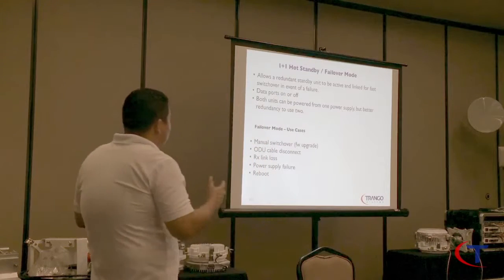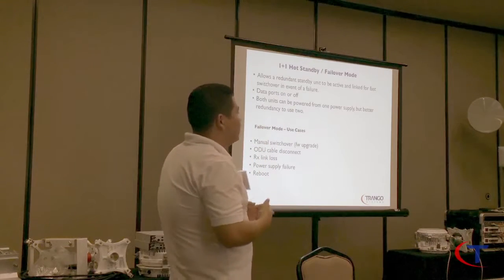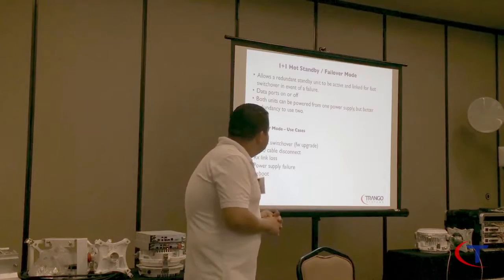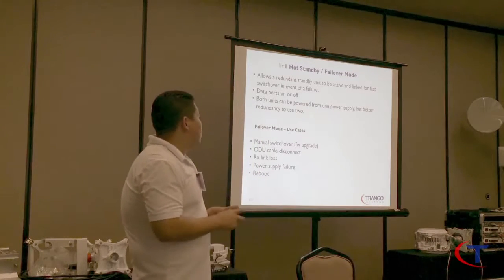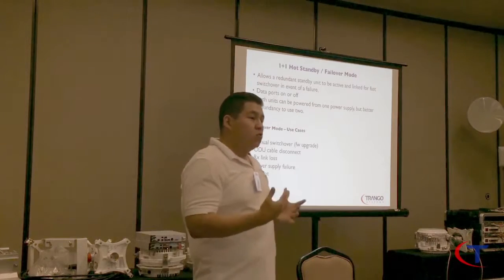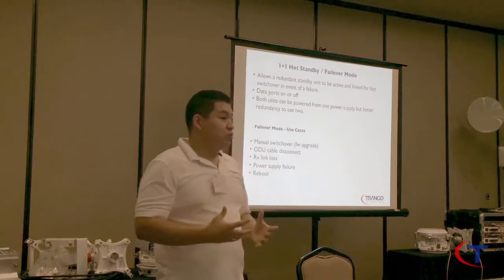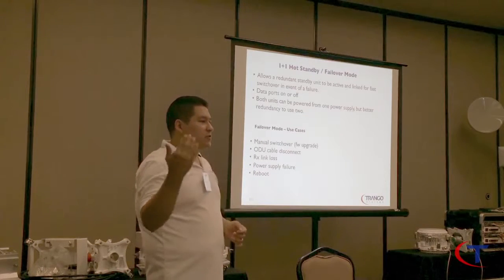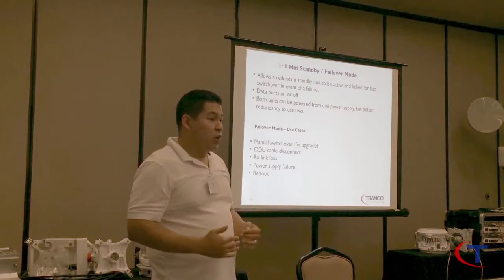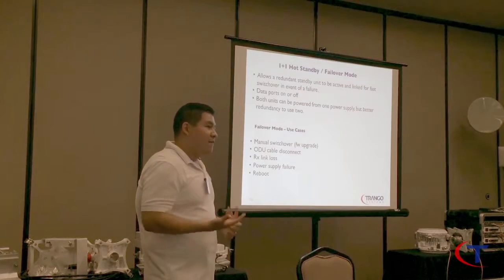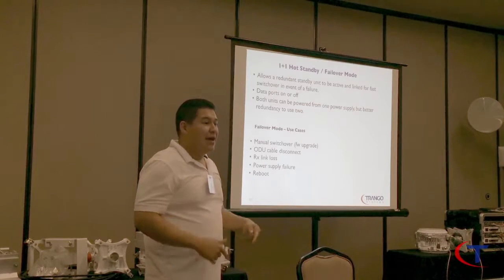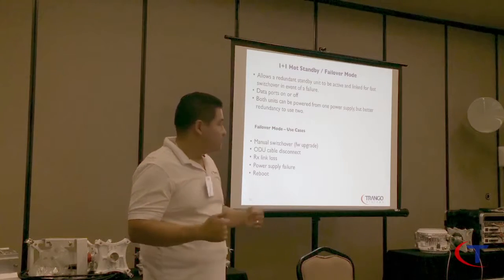Now, what is 1+1 hot standby good for? What are the use cases that we have? Manual switchover. Remember, the 1+1 does not aggregate the actual throughput. It's a single lane, so it's 761 across, and you have your backup, which is again 761. What is it good for? If I need to reboot my master radios, I can go ahead and reboot them without any problems. I will still have service going across the link.